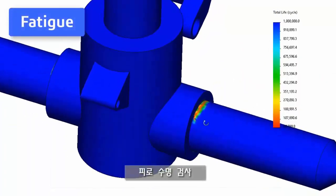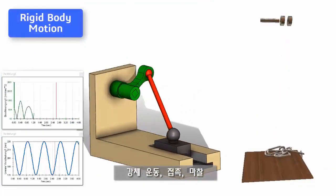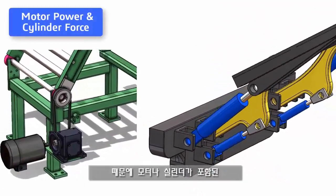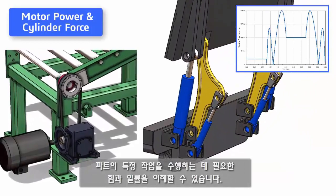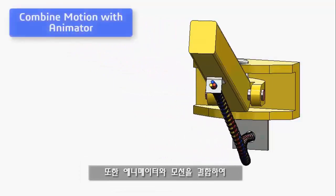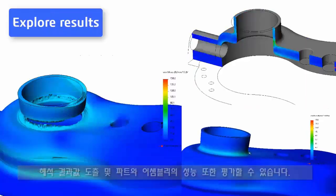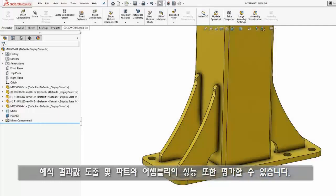Fatigue, lifetime checks. We can also do rigid body motion, contacts, friction, and understand the forces being generated when we have parts moving. So if you're working with motors or cylinders, you can understand the forces or the power that is needed to accomplish your specification. You can also combine motion with animator to create realistic movements. And here we have a cable that is swinging back and forward. And also to explore results, understand the performance of your parts and assemblies.